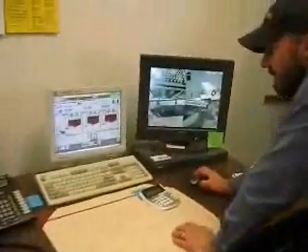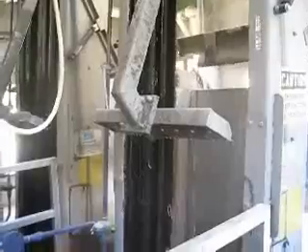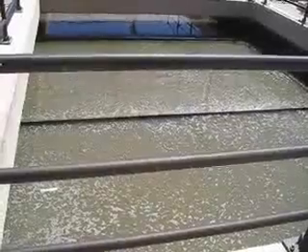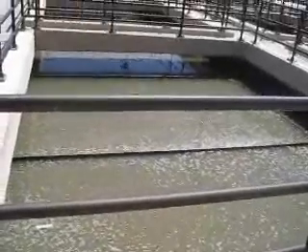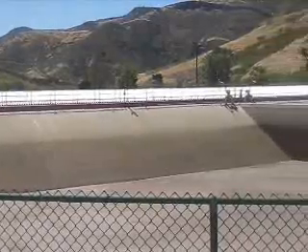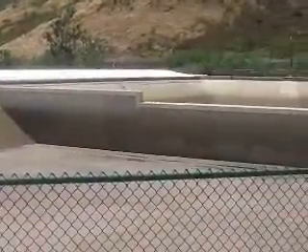Wastewater enters the facility through sewage pipelines from either the north headquarters or the south. Preliminary treatment, which includes rag and grit removal, takes place first. Bar screens filter out large floating material. Then a grit chamber slows down the water for solids to settle. A primary clarifier tank then lets smaller particles settle into sludge. Then the water goes to equalizing basins, which control the amount of water entering the system throughout the day.